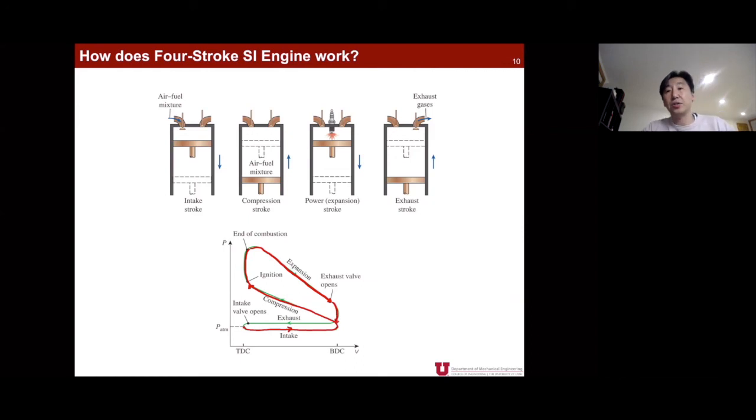Okay, so now we have a very quick jump down of pressure because of the open exhaust valve, and we call that exhaust blow down. But still there is certain burned gas remaining in the cylinder. Then the exhaust stroke starts.